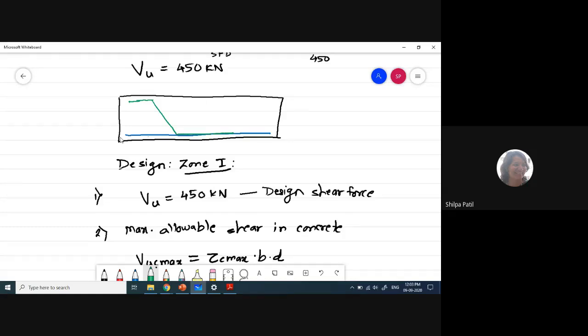Okay, so this is my second bar which is bent up. Now this angle of bend is normally provided as 45 degrees. Then my third bar will also be a horizontal one, and the fourth bar will also be bent up, which will be exactly behind this green color bar. Is the concept of bent up bar clear?